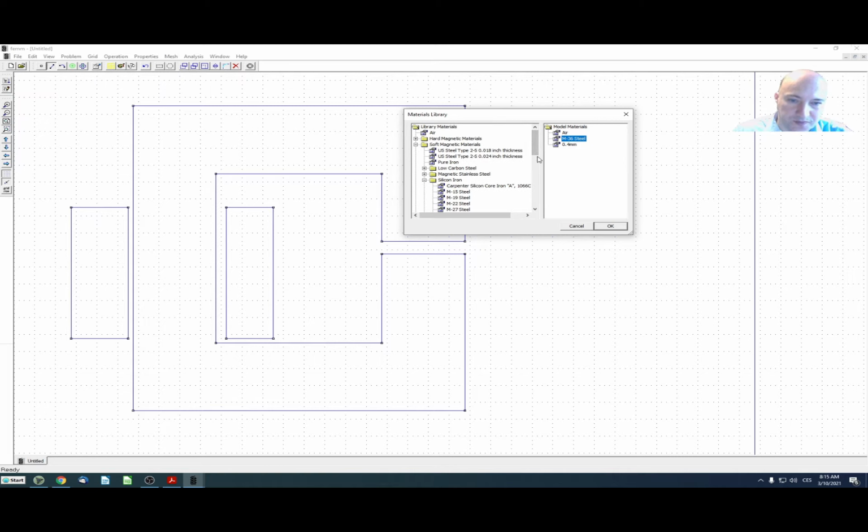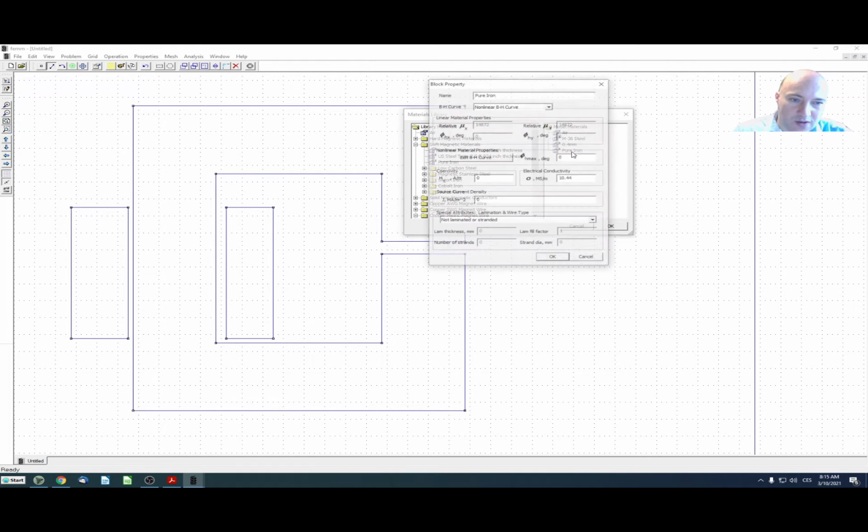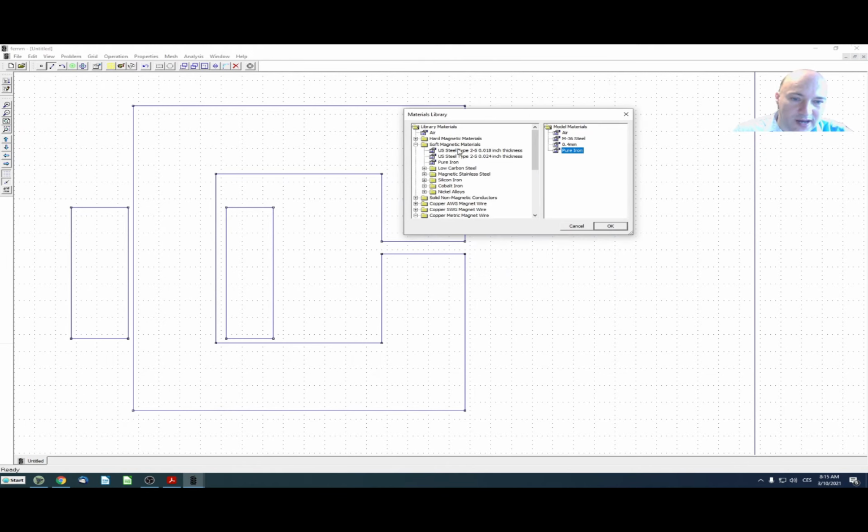and non-linearities. So for example, let me select some iron from the library, and let's select, say, normal iron. Here we have, for example, pure iron. So I will just drag it into my model so that later we can actually see the differences with different materials. Now for the pure iron, you see that this is defined also as a nonlinear BH curve, but you may find that other materials may be defined also as linear materials.